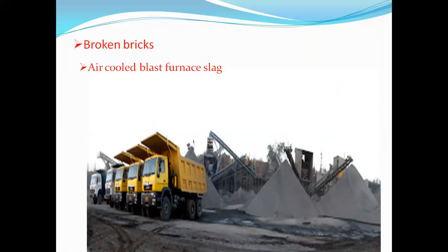The broken bricks are not suitable due to the following reason: they have a low crushing value and poor resistance. So we have to use the broken bricks in work where strength is not an important factor. That is, for rough work, PCC work or filling work, we can use the broken bricks.